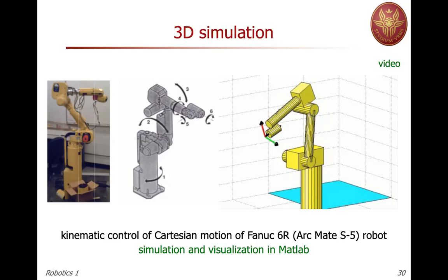So the end effector goes straight to the destination, and similarly for the orientation. But because we have not planned the trajectory here, we are only driven by the error, and we see the full error at the beginning, and then we reduce the error. The transient will be exponential, so we do not have a pre-planned time for doing the task.